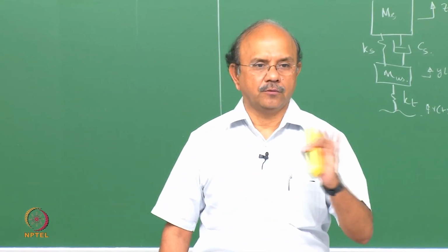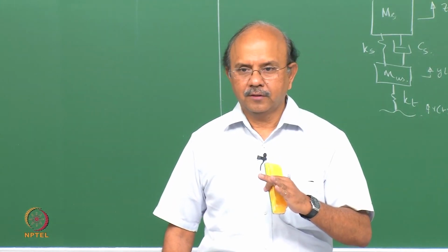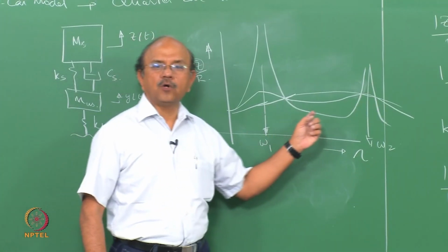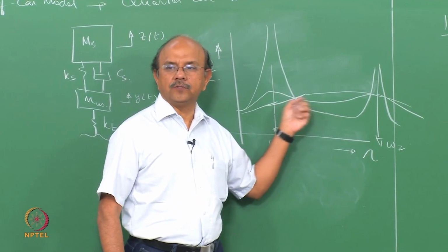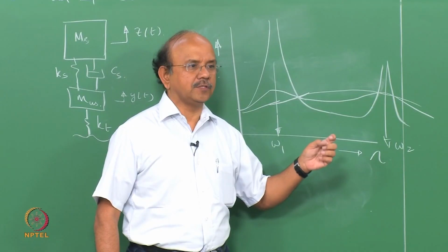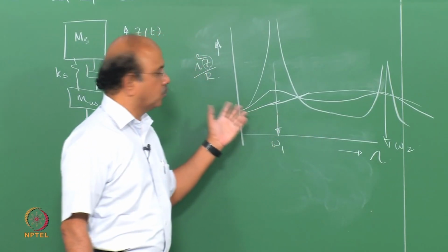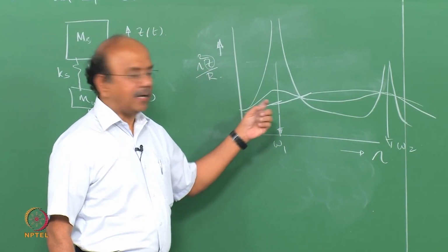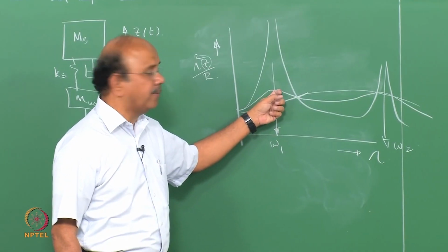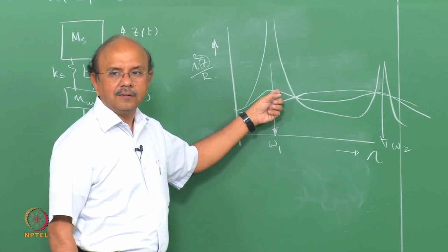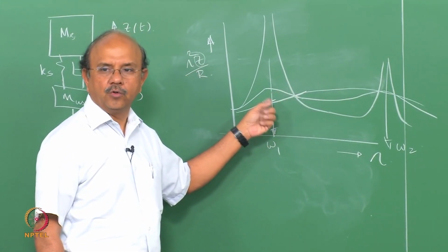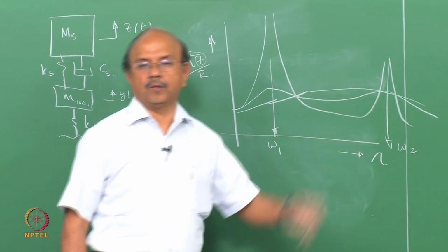R is actually the amplitude of the road excitation. Now, a good damper in one frequency, you cannot say that it is good or it will dampen out in another frequency, and so on. Suppose lower damping is good in one, bad in another. Higher damping is good in one, bad in another, and so on.